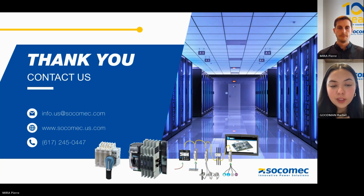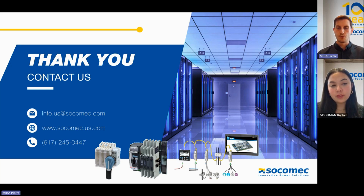Thank you. Another question we have is, what are the most popular STS models in the market in terms of current capacity? So to speak about current capacity, usually when we speak about STS, we speak about a package of STS and PDUs. What we are seeing in the North American market is a combo of static transfer switch and PDU rated together.